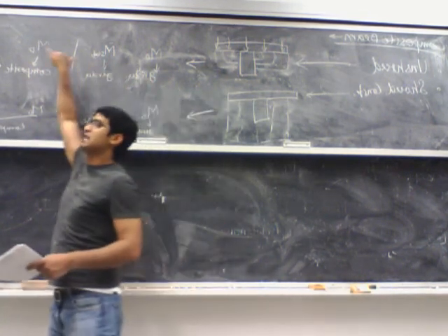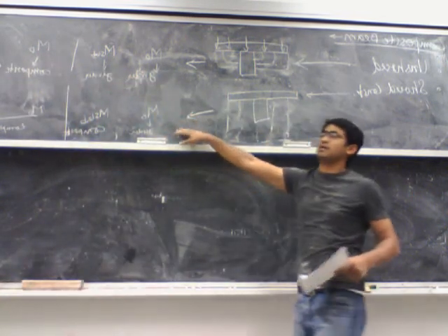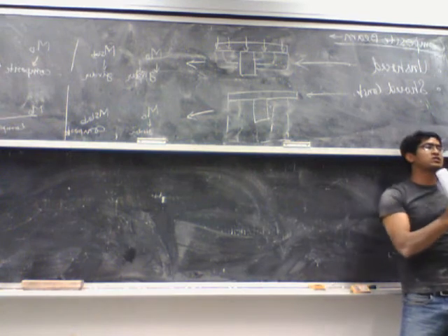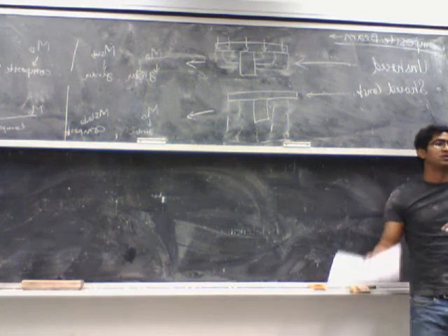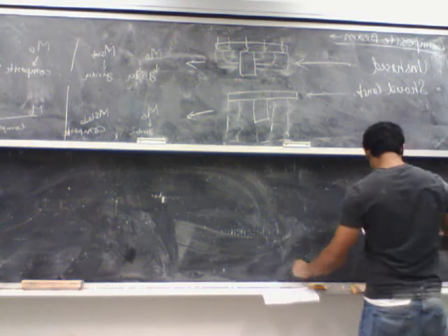In both cases, the total load is still the same. It's M naught plus M slab plus dead load plus live load. So the total load is still the same for both cases. The only difference is how it's distributed between the girder and the composite beam.